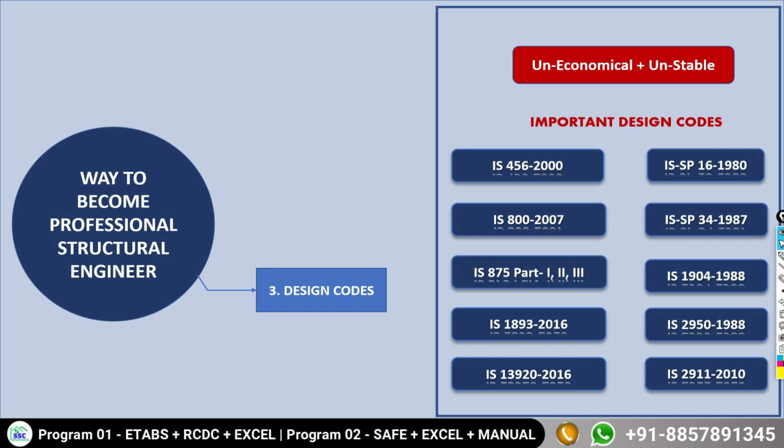This code will tell you what minimum percentage of reinforcement you have to maintain in any particular type of element, beam, column, slab, foundation, whatever element you are going to design. How much the minimum percentage, maximum percentage, number of bars, what the spacing of the bars should be. There are so many things you need to understand. If your column is going to become a long column, what to do with that long column, what additional moment and additional reinforcement you have to provide, everything is given by your IS 456. Then IS 800:2007, the code for the design of your steel structure.